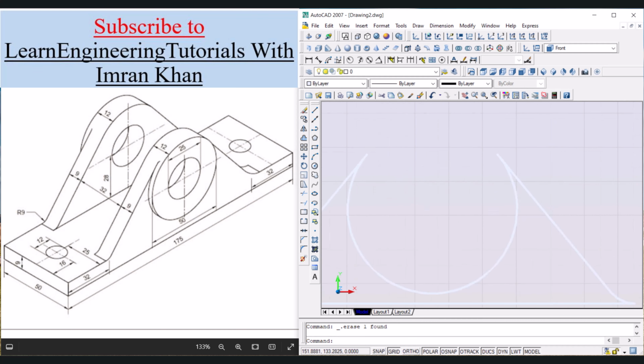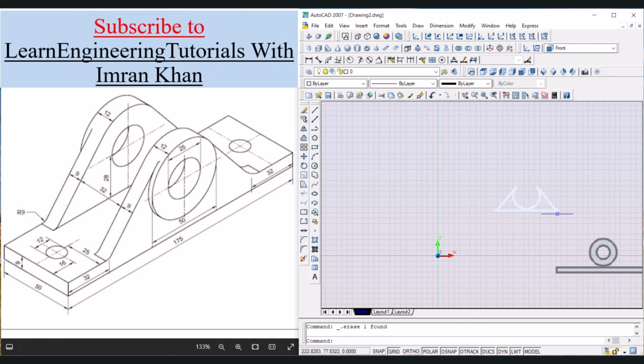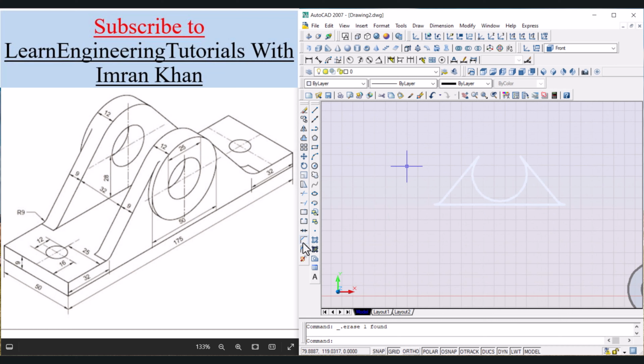Now let us visualize if there is any discrepancy. If there isn't any, then we can use region command. So click on region, select all these objects, 6 found. Now press enter, and now we can see that a region has been created.